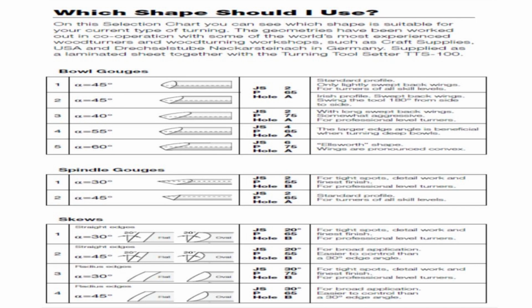Okay, as we talked about, particularly with the gouges, every turner out there has an angle that he likes on the end of his gouge. There are gouges that are a little bit flatter in the end, which is great when you go to the end of a bowl. You can see how you can begin to sweep back the edges of that bowl gouge, which makes it very nice as you're turning the outside. It gives you a much larger cutting area.